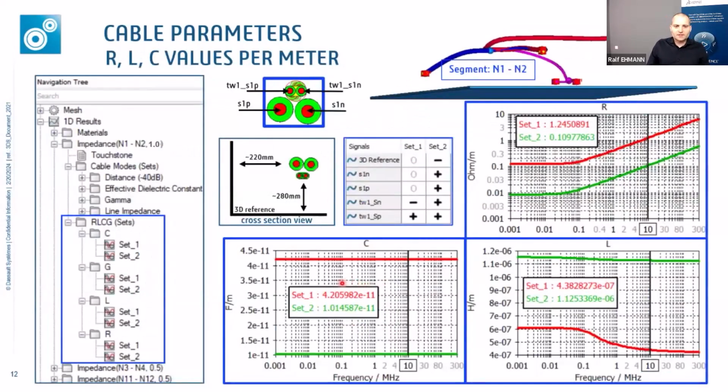Also with the same settings, in the same simulation, you are able to directly get the partial information about the resistance, inductance, and capacitance parameters of that cable, which I think is very useful if one wants to compare with the data sheet. And in relation to the capacitance, it's important to always have the 3D model of the 3D environment around the cables, the cable segments exactly as the user wishes. But this is done because we just did that import directly from our CAD software, or 3D experience in this case.